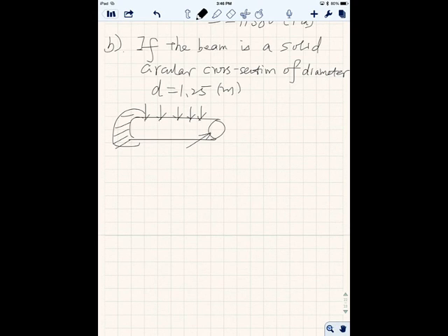The equation we need to use is the maximum stress equals 32 over pi d cubed, times the square root of My squared plus Mz squared. Okay, so this is the equation we need to use, and I didn't really mention it initially because I figured it's easier if I mention it while we see the example, so you can just remember right away.